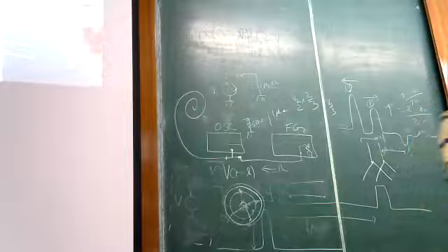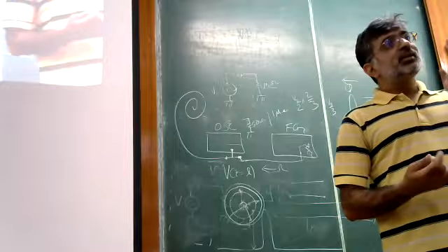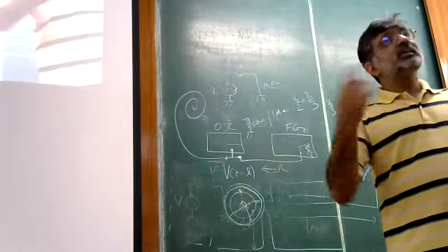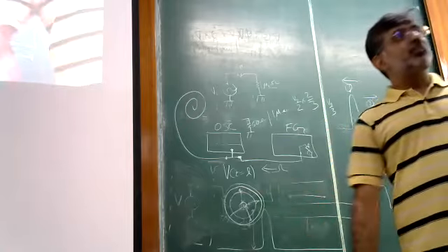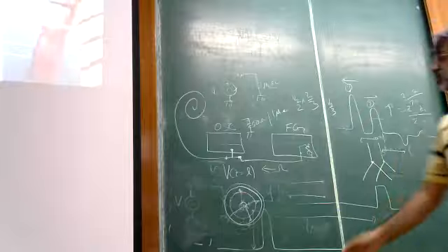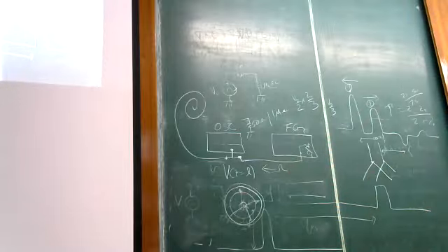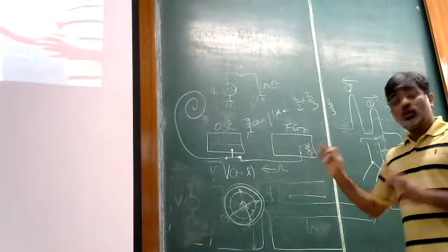Right? So if you remember your Poynting vector from your electromagnetism class, that gives you the direction of energy propagation, and that goes as E cross B, right? So here very nicely E and B are already perpendicular to each other. So the direction of propagation is perpendicular to that. So everything, and this is the most sort of ideal transmission line setup you have, because here the properties of the wave at different frequencies don't change much, as long as you are at low enough frequencies.